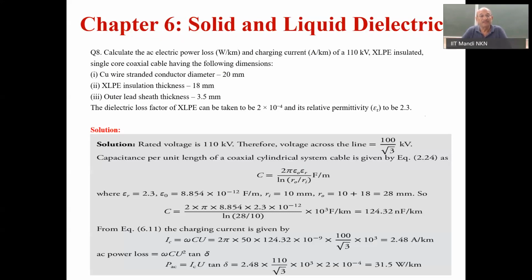will be which voltage? Line to line or line to phase? Sorry, line to line or line to ground? It will be line to ground. So line to ground, that is the phase voltage, actually will be 110 kV divided by root 3.